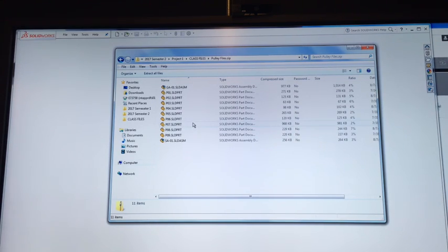Before you submit, or before you email it to your boss, or to a client, or to your supplier, it's a good idea to actually check your files. Make sure that what's in there works, there's no issues. To do that, you have to unzip the files. You can't open an assembly from a zipped folder because it won't be able to find all the references properly.